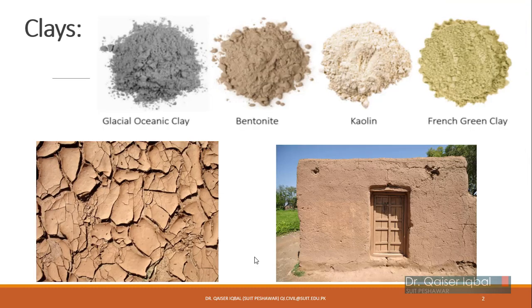Okay. Last time we discussed various types of soils based on the classification, starting with gravel as the largest size, then followed by sands, which are smaller in size than the gravel, and then silt, which will pass through sieve number 200. They are small as well, and then microscopic and submicroscopic flaky clays. So we already discussed in detail sand, gravels, and silt.